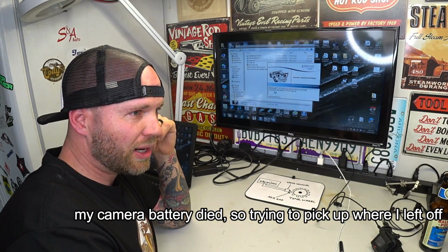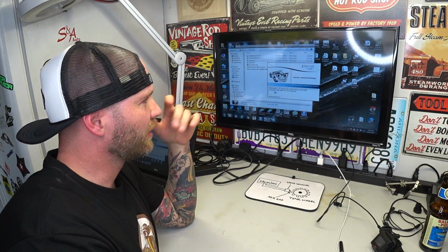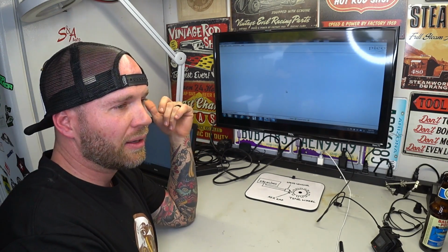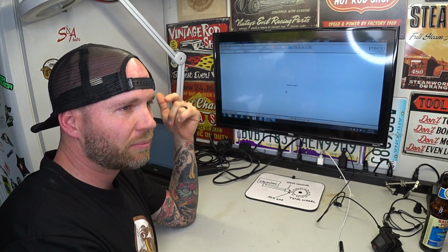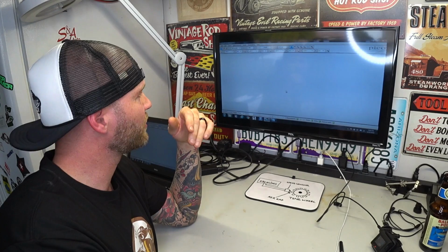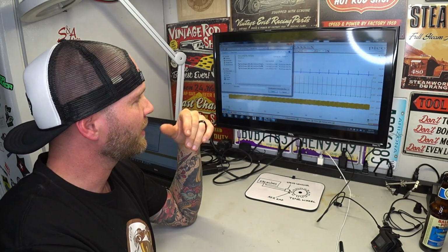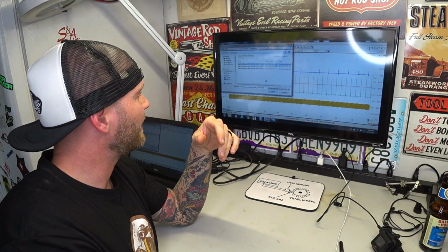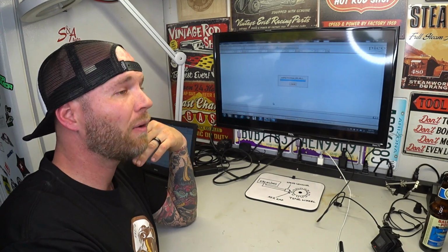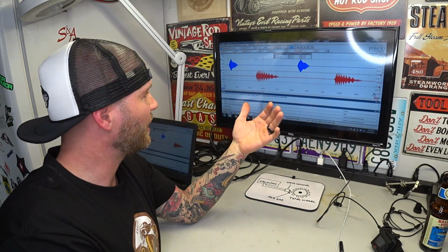So these frequency channels are nice, because like I was saying earlier, the ABS sensor produces an AC signal. It goes into the electronic brake control module, and that electronic brake control module interprets that signal and outputs something different on what we see on our scan tools.